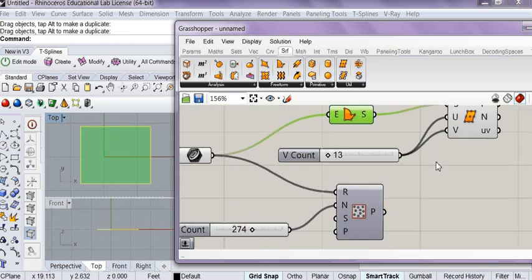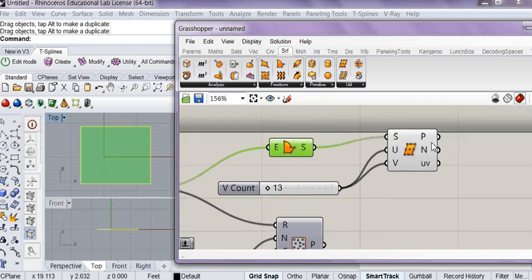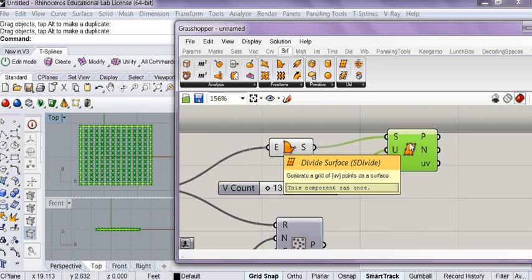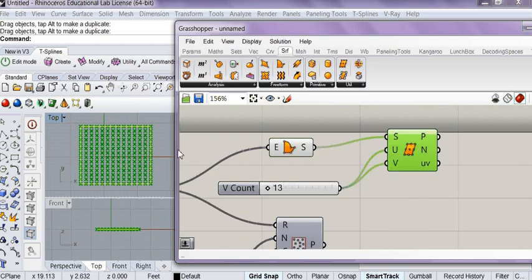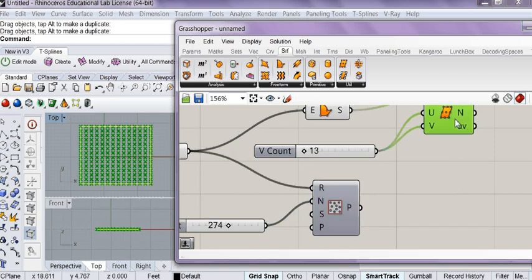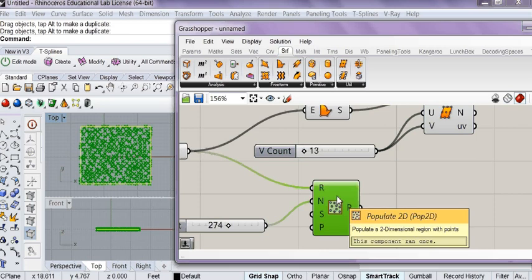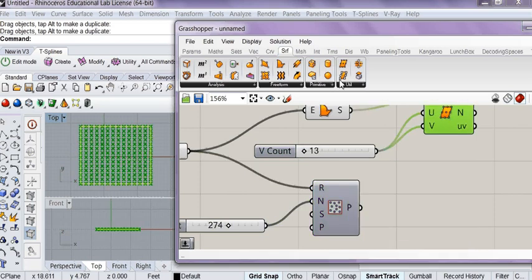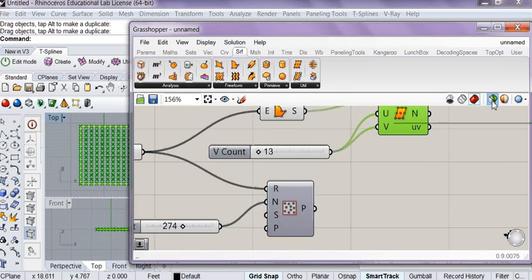By this way, you can easily just go through. I want to know what this component do. I just click that. As soon as you select this component, Rhino or Grasshopper will display the result of this component. If I select this populate 2D, see, really depends on your selection. The display is different. That makes sense? So this green color bucket, this cylinder is very useful. Okay.